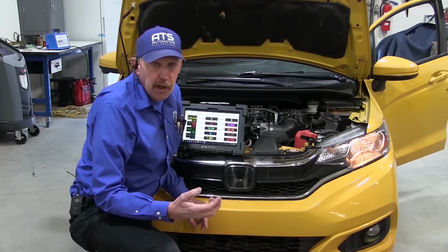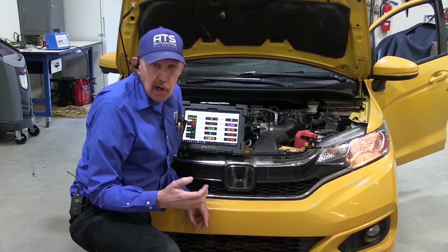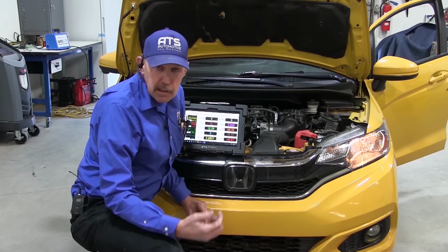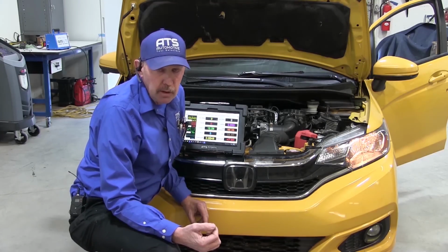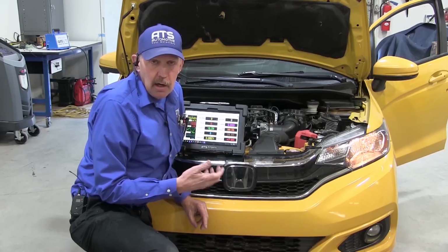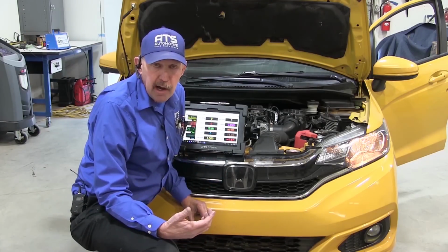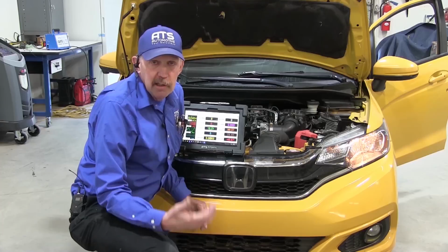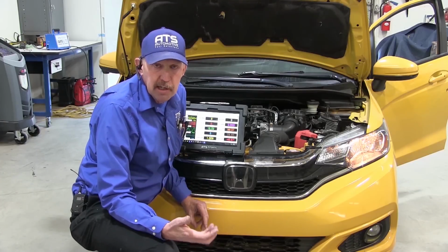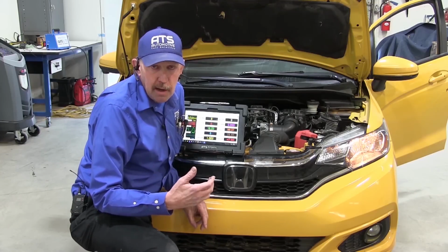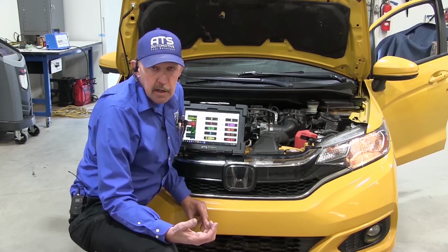We went out, we drove the car. We saw the trims aren't linear. They're going from minus 45 to minus 20. Now that would tell me that I don't have fuel contamination, and it also tells me that the purge valve isn't leaking, because when I lose all the vacuum, I couldn't still be taking away 20%. So the fuel isn't contaminated and the purge isn't leaking.